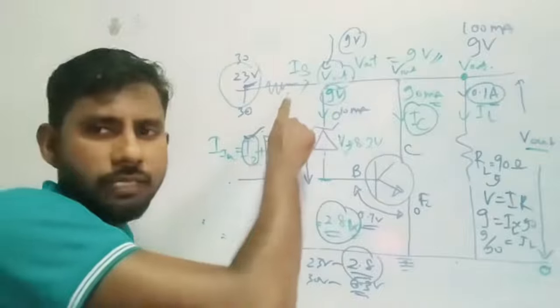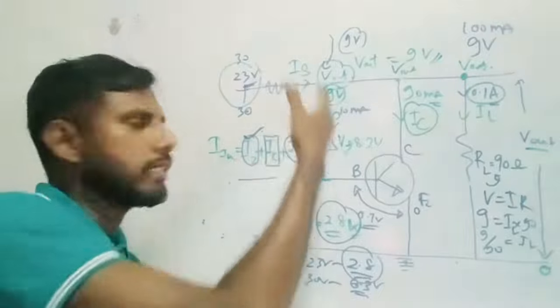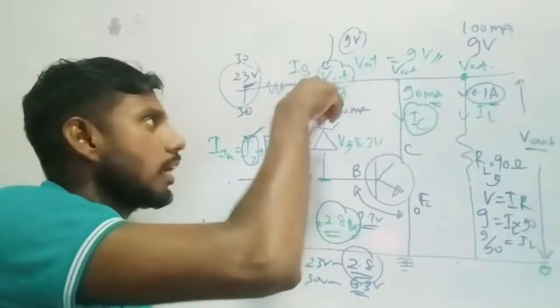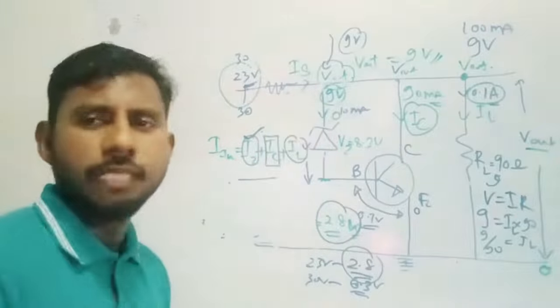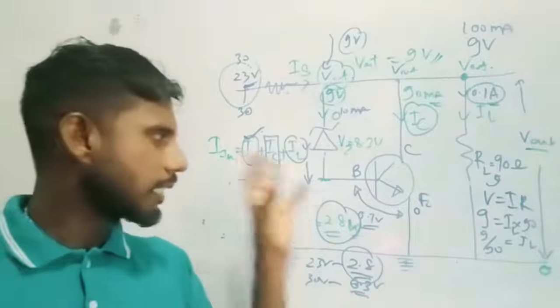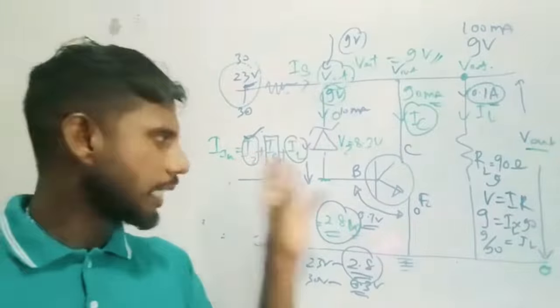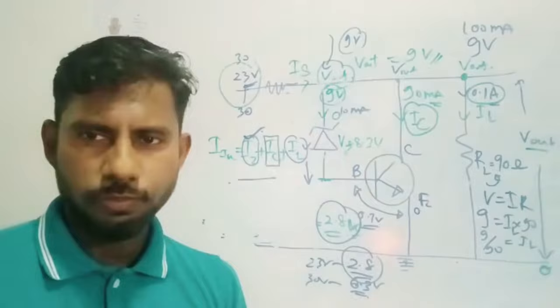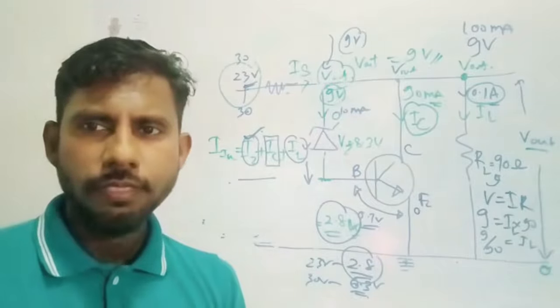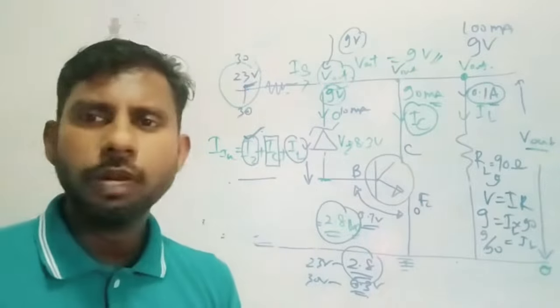Whereas in any case, if IS is increased, the additional current will be sent through this Zener diode. So with this combination of Zener diode and transistor, it will make sure the potential V out is constant, right? So that of course you have to write.